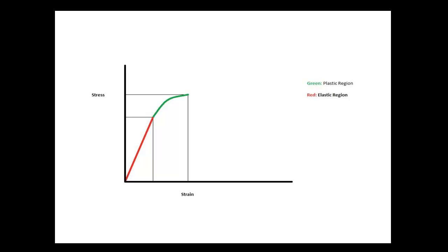In the plastic portion of the stress-strain diagram, the curve is not linear. When the stress passes the yield point, the material starts to deform much more rapidly. Unloading is, however, linear and has the same slope as the elastic portion of the plot. This allows a material to be strain hardened because subsequent loading will follow the same line as the previous unloading. This allows the material to undergo more stress before it starts to deform plastically.